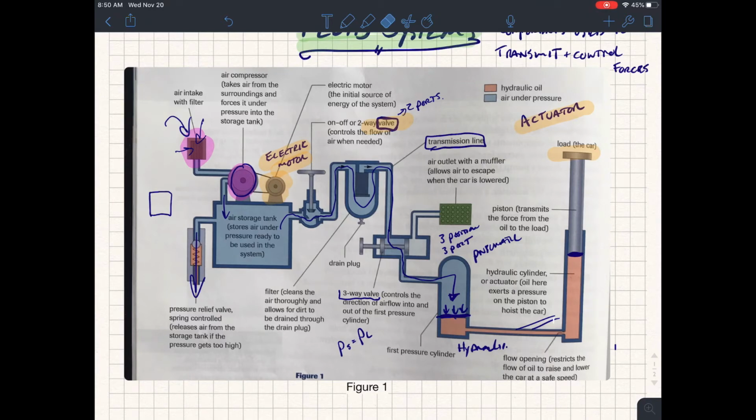Don't be confused. As we have a force being pushed down in the hydraulics, the fluid, which is not as compressible as the gas, transmits that force to all parts of the fluid and enables us to lift the car. The actuator is this mechanical plunger. Remember, the actuator transmits the fluid force into an actual mechanical force of whatever we want to have happen.